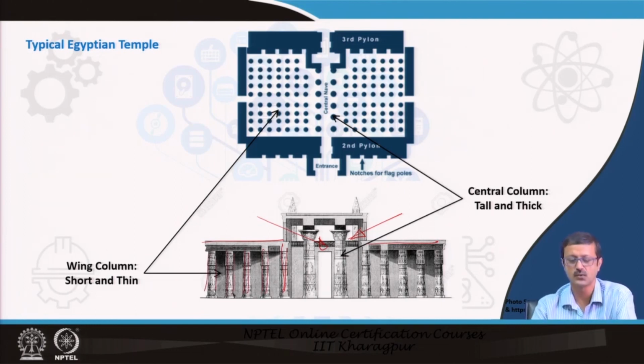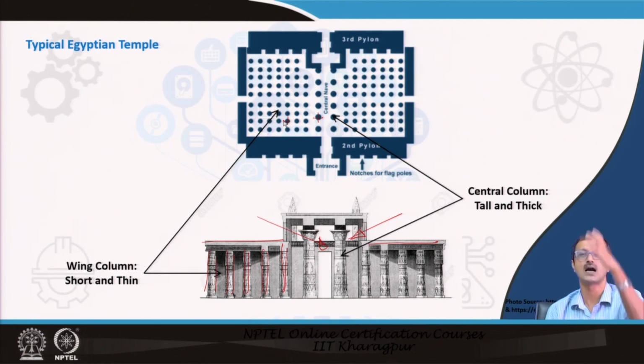So you have two types of column: the central one is high and the wings, or the flanks, are lower. You can see the dimensions also from the plan: the higher dimension is in the central one, I am sorry, and the lesser diameter is in the flank. Why? Because if you want to put a higher, longer column, you have to increase the diameter to take care of your critical stress, the slenderness ratio, and your Pe, that is the critical value of the force also.